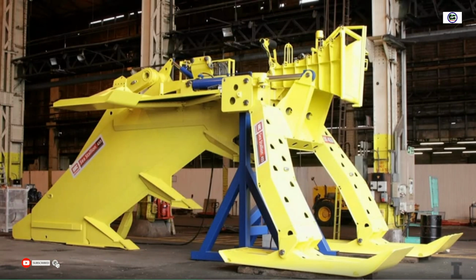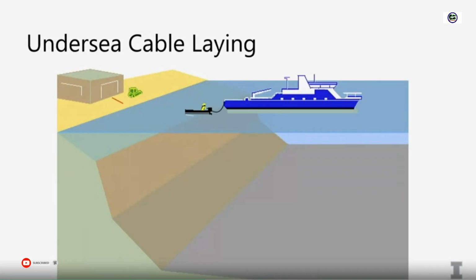To see an animation of this, this is how a cable is deployed. You have your ship where you're spooling out that cable. You attach it to your co-location facility on shore, and you have a private beach. You're going to pay for this beach, so you're not going to have people going in and interfering with that cable. You're going to bury the cable there. You drop it down until you get to a certain depth offshore.